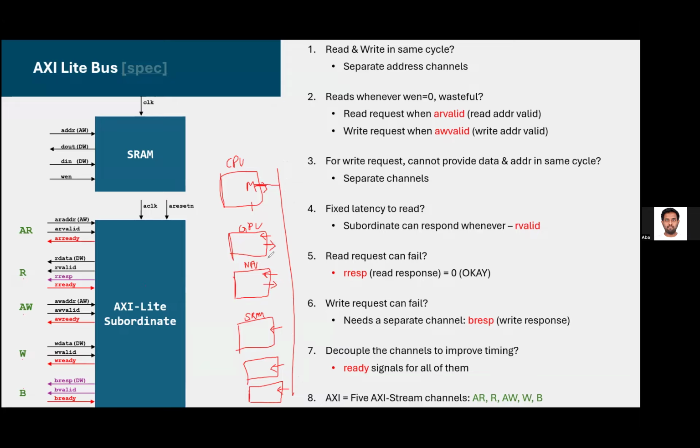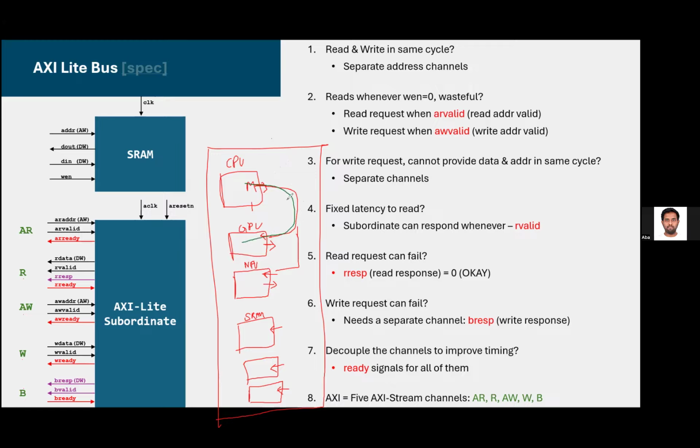So now the thing is, once you put this together into one chip, these are all connected, right? Let's say like this, all connected, and you put this together into one big chip. And let's say you send it to the PD team, and when they do the physical design, they find there's a long path from all the way from here to here, specifically in the address channel, the AW channel. And that is affecting your frequency, and you can't meet the timing. So now what do you do?